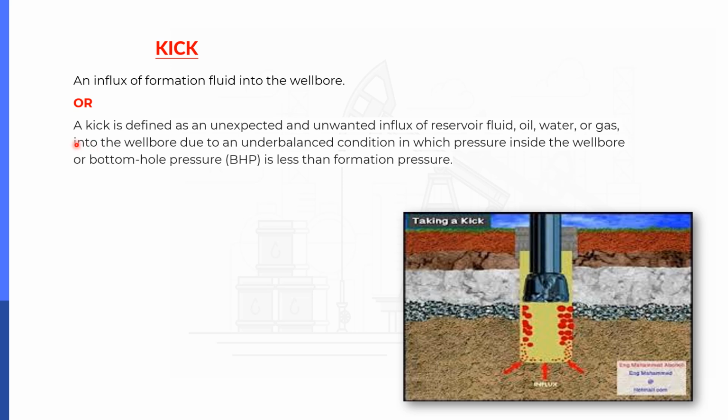Another definition: a kick is defined as an unexpected and unwanted influx of reservoir fluid, meaning the bottom fluid, oil, water or gas, into the wellbore due to an underbalanced condition in which the pressure inside the wellbore, or the bottom hole pressure, is less than the formation pressure.